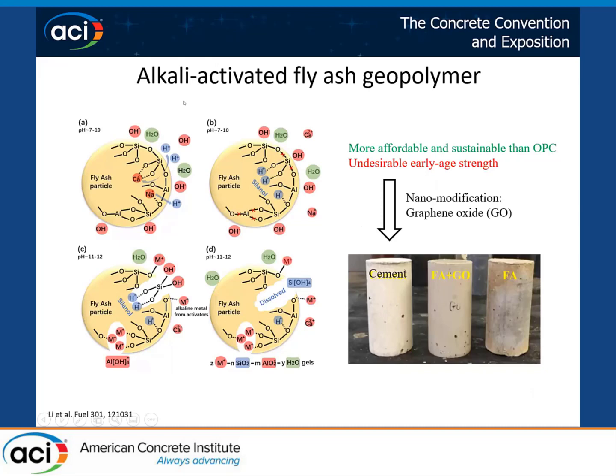When fly ash meets alkaline, the alkaline starts to attack the fly ash, and the positive ions inside the fly ash exchange with the positive ions from the outside. The chemical bonds are broken, and the fly ash breaks into many small units. This process we call alkaline activation, also depolymerization. Then those small units connect with each other and generate new hydrates. This process we call repolymerization.